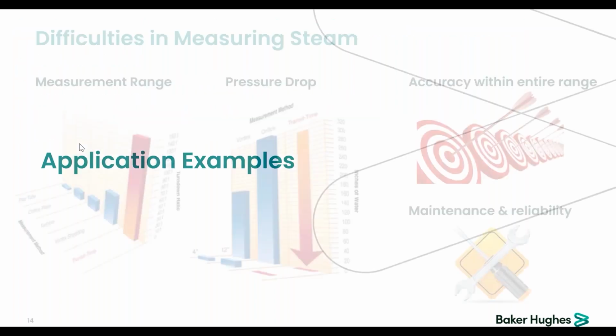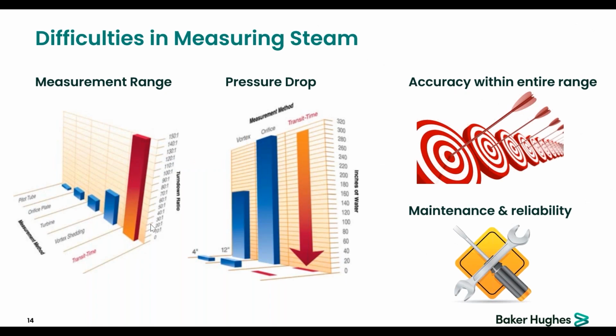Now, if I look at applications such as steam, we have more and more demand for steam measurement using ultrasonics because of the absence of pressure drop. The rangeability is quite wide, especially in utilities where steam demand varies largely between winter and summer, for instance.